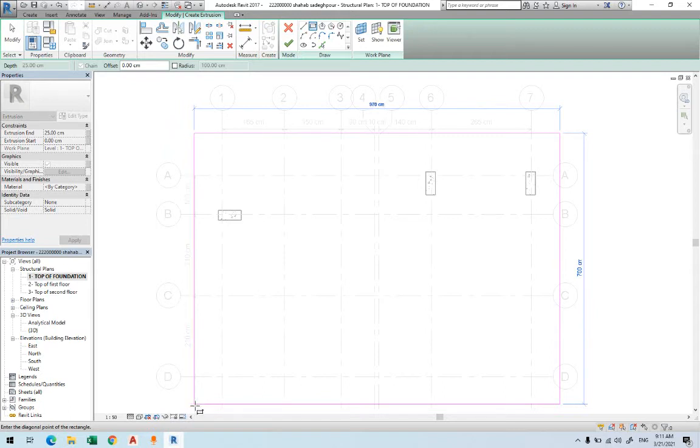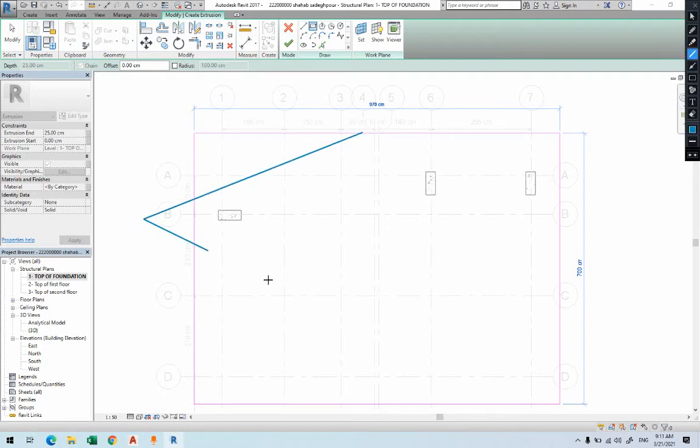And then what will we do? We extrude it down. It means that we're trying to draw the top of the foundation like this. I mean, in 3D, as I'm looking at it. We're trying to draw the top of the foundation and extrude it down by the 40 centimeters that we have. So this level will be the top of the foundation, the level that I have, and the extrusion will be here. So we will draw this one to see how it works.